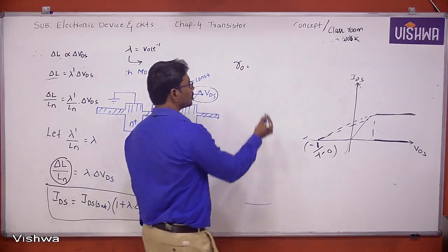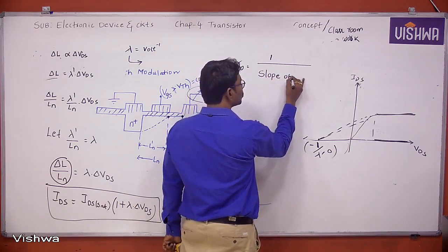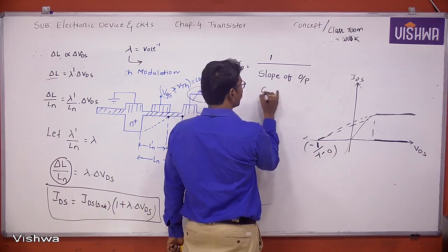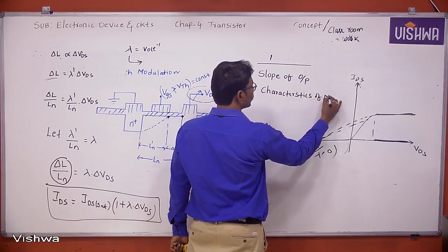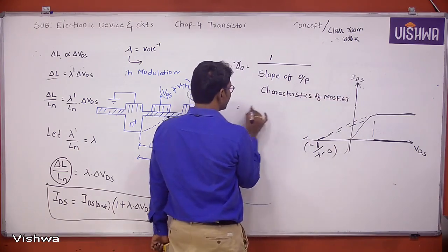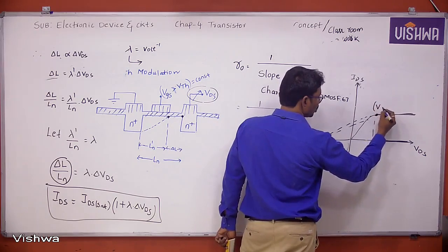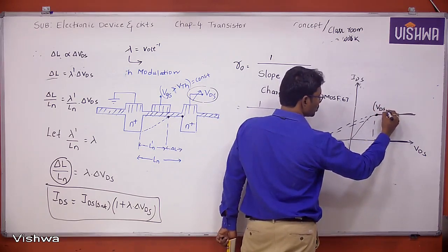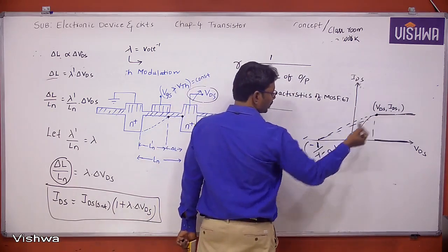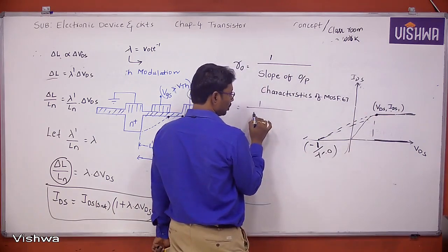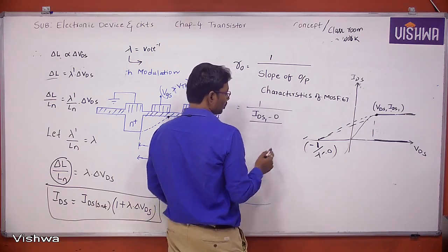Output resistance is nothing but the reciprocal of the slope of the output characteristics of the MOSFET. What is the slope of this curve? For calculation of the slope, assume this point is VDS1, IDS1. Now what is the slope here? Y2 minus Y1 by X2 minus X1, that is IDS1 minus 0 by...